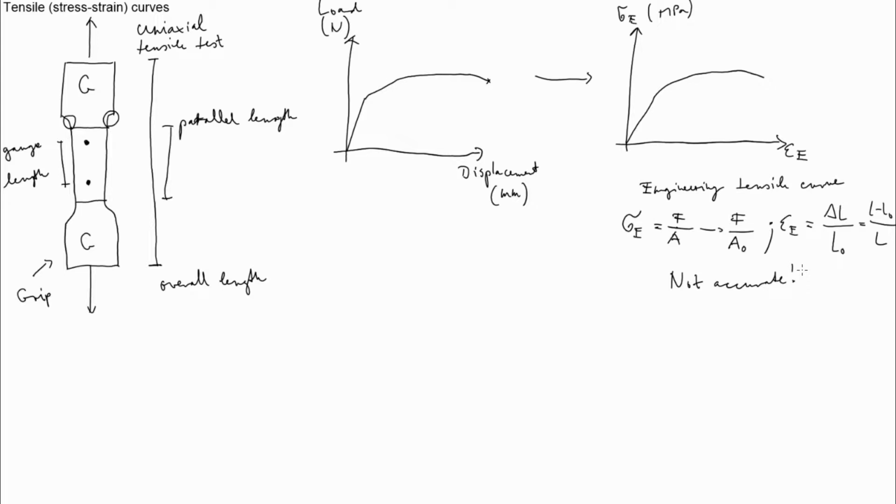Because you are using the initial values of your specimen, but during the testing the material will change its shape, so therefore the area will change, and you are not getting the correct stress values, especially at large strains.